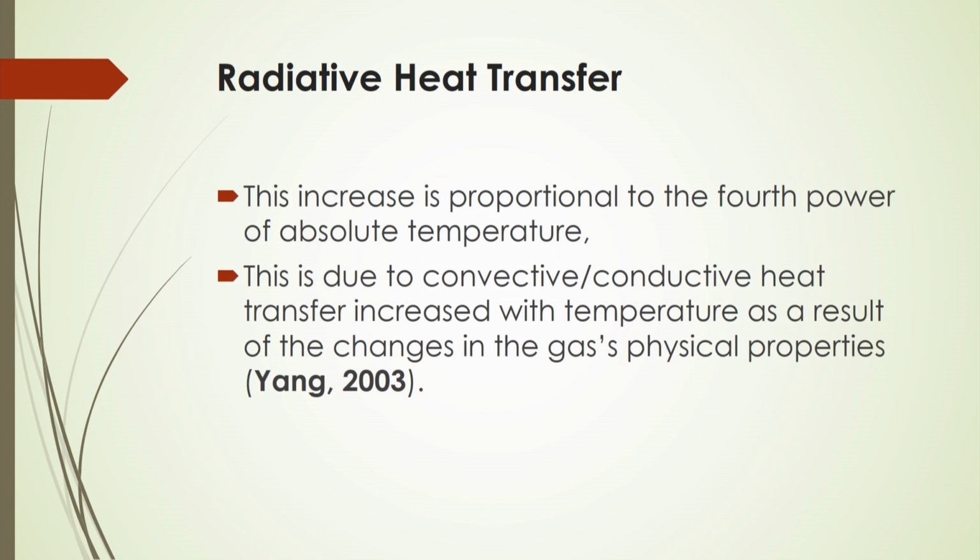Now, this increase is proportional to the fourth power of absolute temperature. So this radiative heat transfer is proportional to the fourth power of absolute temperature, and this is due to the convective or conductive heat transfer increasing with the temperature as a result of the changes in the gaseous physical properties, that is reported by Young 2003.